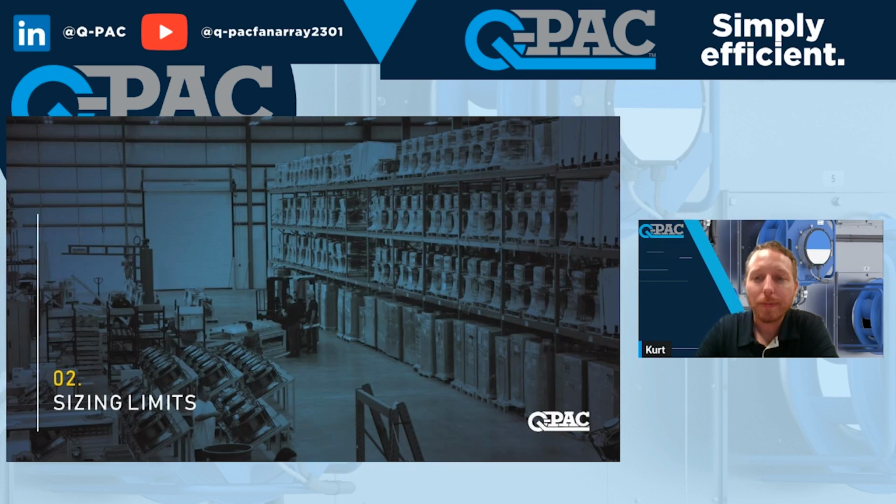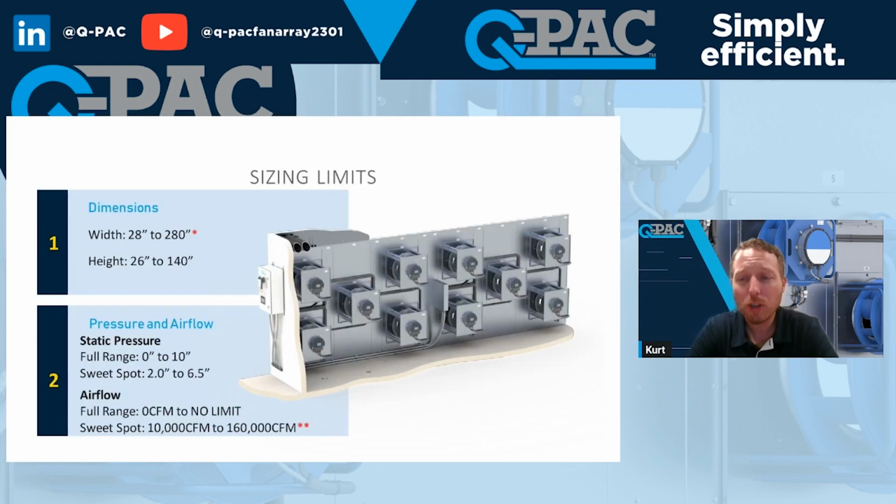Sizing limits. As far as width is concerned, 28 inches is as small as we'll go, up to 280 inches. I have the red asterisks in there because really we don't have a limit on the width. You can stack our fan systems as many as you need to infinity, really, and get as much airflow or as much width as you want.